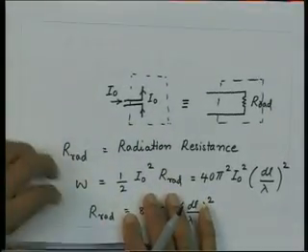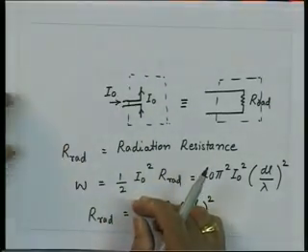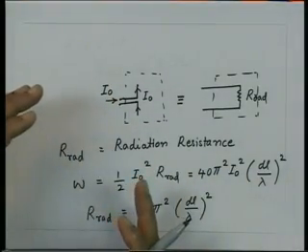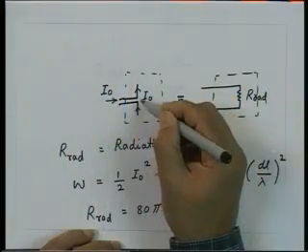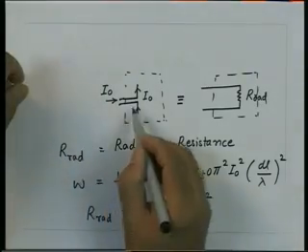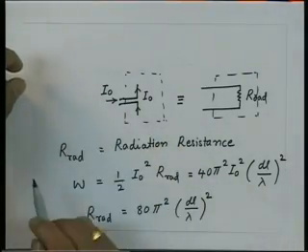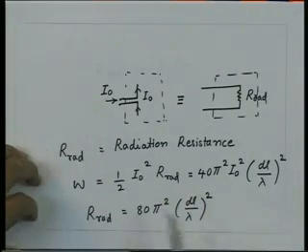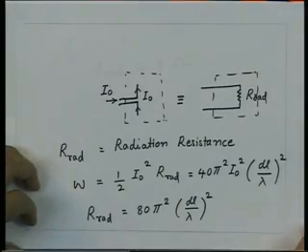Firstly, if I want to excite this structure, I will be using some transmission line to connect it. We have seen that coaxial structures have characteristic impedances of the order of 50 ohms. If I take a parallel wire line, the characteristic impedance will be a few hundred ohms. So practically this load appears almost like a short circuit compared to the characteristic impedances. So you have a great mismatching problem between the transmission line and the antenna when you try to excite this antenna. Secondly, because of the low radiation resistance, the power radiated by this antenna is very small.